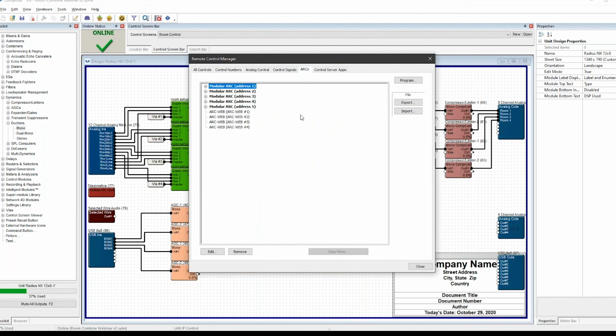Like I said, I can't physically show you our ARCs, but this is the programming I've done. With the ARC K1Es and the EX4s, each microphone has its own volume, where you can go back between the two of them with the encoder button itself, and then the radio buttons on each EX4 control the BGM source. In this case, there were 4 sources, even though I had the 8 buttons, but that was my fault. So each room has its own individual control.